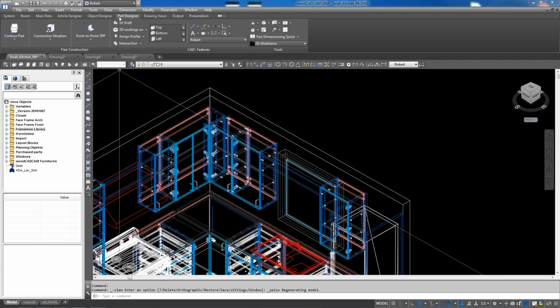This is going to be an L-shaped soffit, I guess. The soffit's L-shaped on this one. Is the soffit all the way around, both walls here? Yeah, I was going to follow the upper cabinets. Okay, so just switch back to your plan view again. Just draw a polyline to represent the soffit.